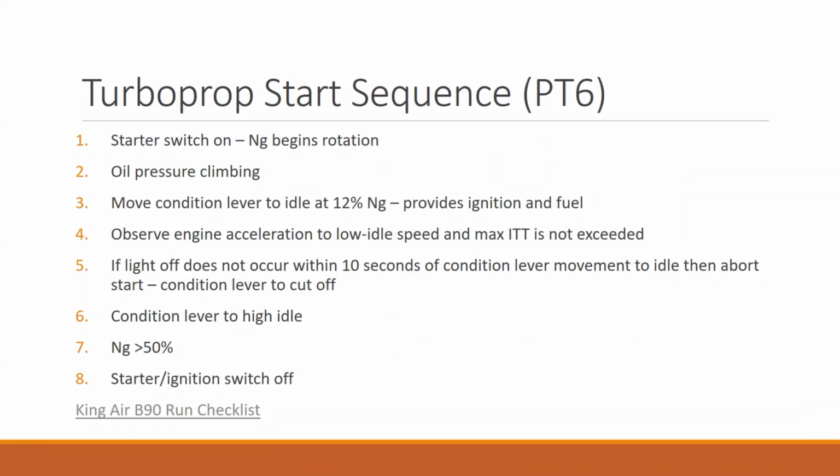We want to verify that there's oil pressure, and we don't want to be putting all that extra load on the engine for a long period of time. Although most of these, like the PT6, you can run in feather all day long if you want. It'll sit there just idling along. You don't want to pull power, you'll over torque the engine. But you can idle in feather all day long if you want. Your cabin will stink like exhaust, but you know.